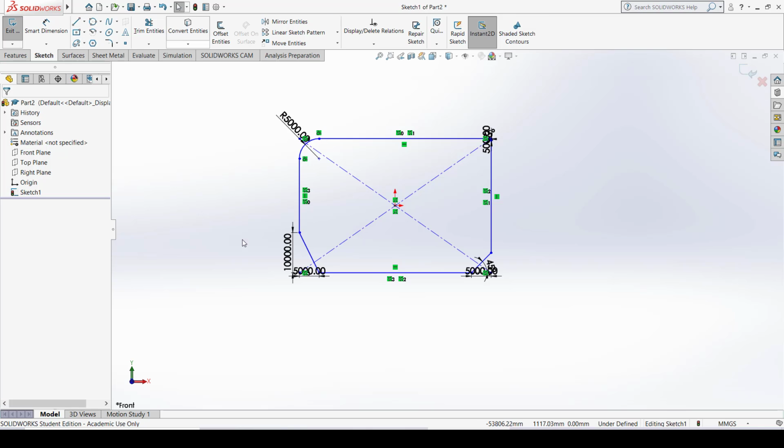So this is basically the basic structuring and drawing of all these basic elements. In the next lecture we discuss how to constrain things. That is the major part of this tutorial series: if you constrain things properly you will get everything further in a systematic way. If you constrain things wrong, then there are chances that your structure is not converted to 3D properly. There are some distortions which are very difficult to remove later on. So in the next video we discuss how to make maximum use of constraints instead of giving dimensions every time. We can use constraints a lot as compared to giving dimensions to each and every element again and again.